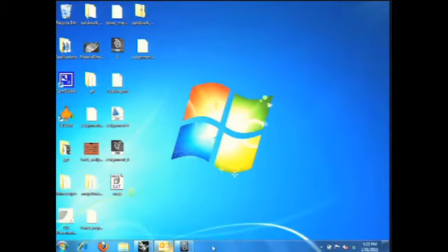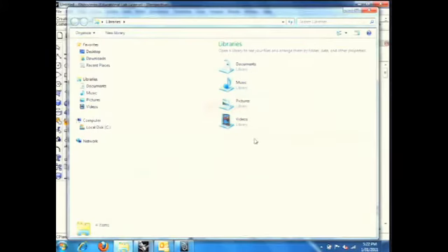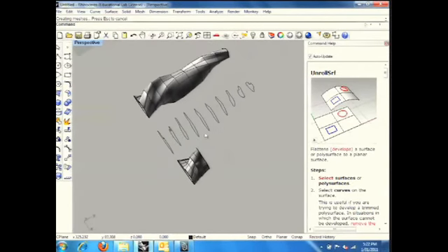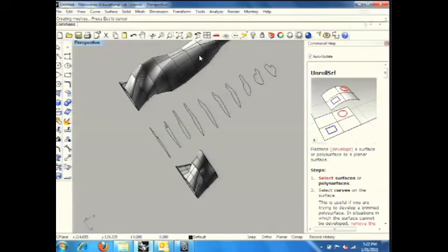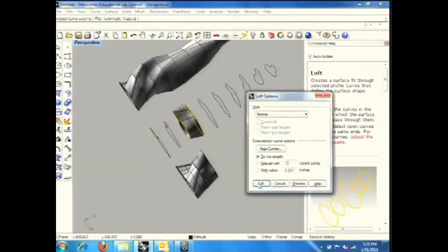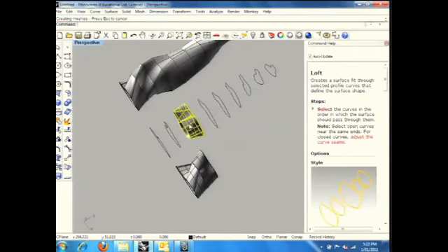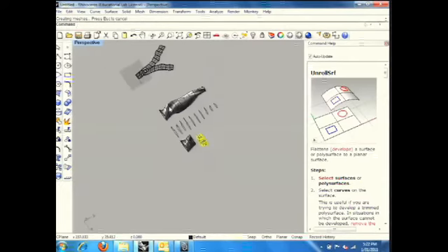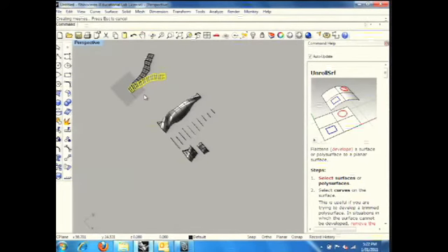That is a big surprise. All right, let's keep talking about unroll. So we know the trick is you want to make sure you pick up only 2 lines and then do the loft. So the curve you generate is only 1 degree curve. In this case, you can do unroll surface. Enter. So you can see that surface will be generated right here.